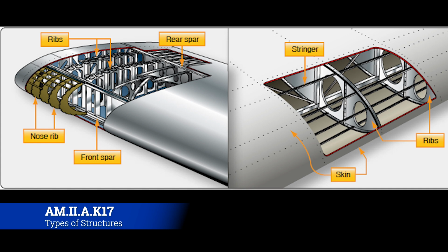But some aircraft have a single spar and everything else connects to that spar, and that's how the wing is designed. Some of them have multiple spars. It really just depends. Now the definition of a spar is it's going to run from the wingtip to the fuselage, and many times through the fuselage into the other wing. But that's what the spar does.